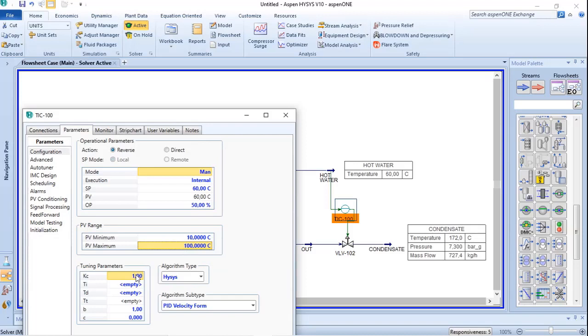Besides that, I need to inform the PID controller parameters, and I will start with 0.5 and 1. You can leave the differential part empty, or you can add a value to help you in your tuning control. Most processes don't need the derivative, but I will not get into details about that. At least the Kc and Ti you need to have in your PID controller.